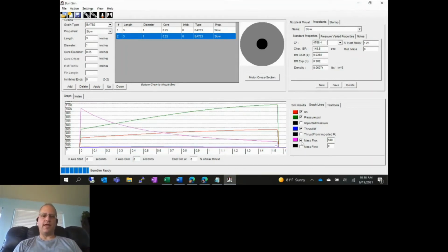One way to measure that is what we call mass flux, which is basically a measurement of how much gas is moving through how much space. I apologize, I forget the exact definition off the top of my head. The higher that number is, the more it translates to gas velocity, or it's a representation of gas velocity. So the higher that number is, the more erosive burning potential you have.